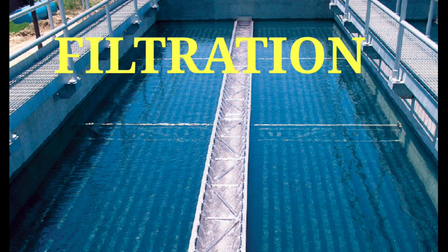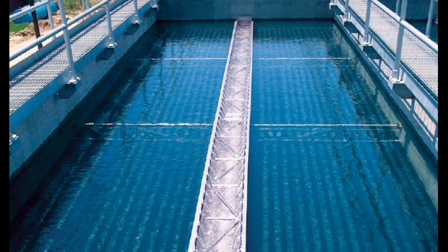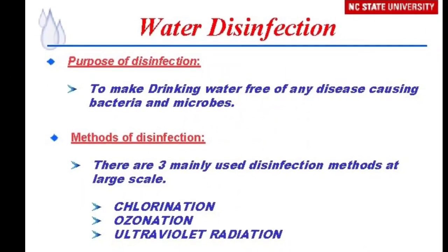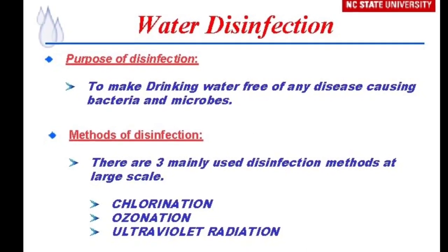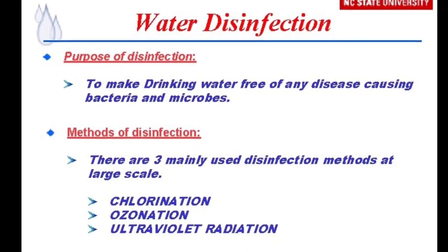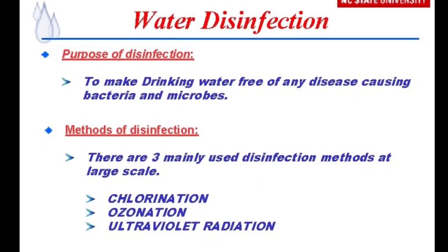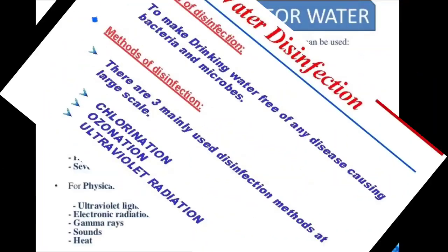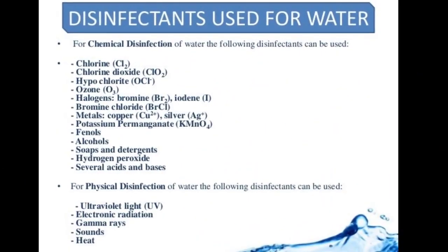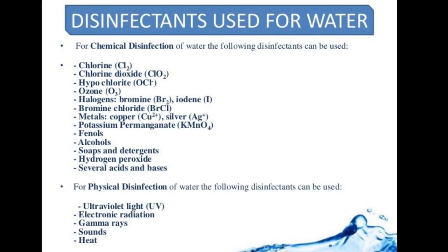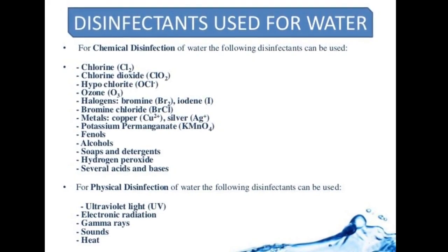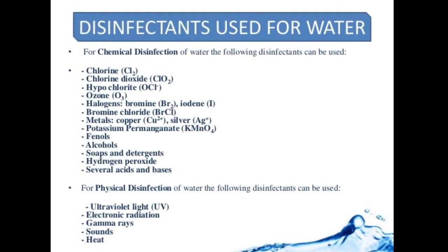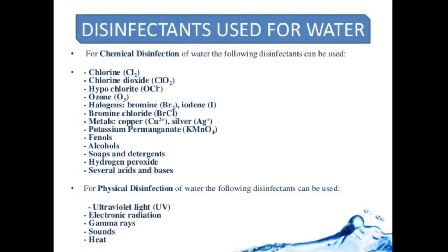After filtration, water also contains microorganisms, pathogenic bacteria, or disinfectants. So a disinfection process is required to kill them. The remaining water has now had the vast majority of its impurities removed, but it may also contain bacteria, viruses, and microorganisms. In order to kill these elements, it must be treated with enough chlorine to be effective, but not too much, as too much chlorine affects the taste and odor of water.